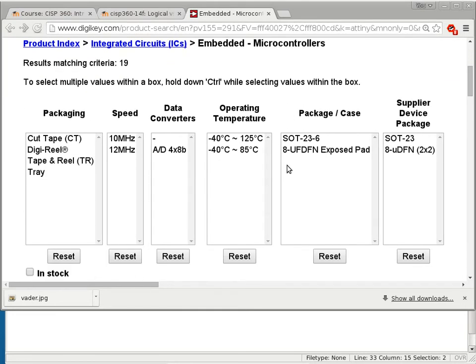A microcontroller is a single chip that has everything that you need to run the program. So it has storage for the program itself. It also has storage for your variables. At the same time, it has all the circuitry that you need to control the output of a pin or to sense the input of a pin. So these things are suitable for what we call embedded system control, where you have a switch. Someone can press a switch, and you want it to actuate, turn on something, or do something similar to that, automation stuff.